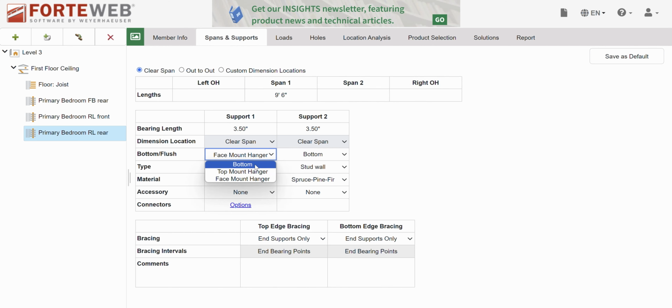Okay, let's do this front one here. This one's going to be a little more complicated, but we can take care of it. Let's grab the span while we're here, that way I can forget in a few seconds. 9'6", basically. Let's try to remember that. Sometimes it serves to copy different beams depending on which ones are similarly loaded, but that's being really specific. You don't really need to. This is like saving seconds when you have hundreds of beams to design all day long.